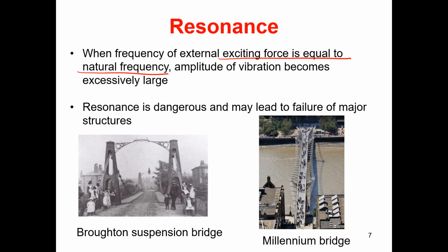And the other case is the Millennium Bridge in London again, which was supposed to open in the early 2000s, and it opened in, I think, 2001. It was a pedestrian crossing essentially. The natural frequency of the bridge was very close to the step frequency of the pedestrians walking on the bridge. So what happened was people were seeing a lot of big movement on the bridge, and they couldn't control this, and they couldn't walk on the bridge essentially. So they had to close the bridge and work on it for 2 years to reopen it.